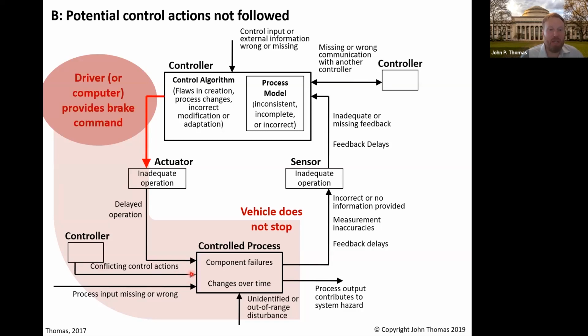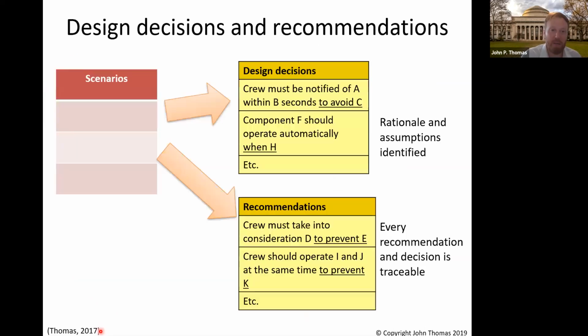That's really interesting. As we get into autonomous vehicles, should the autonomous software at the top here maybe have the ability to override ABS if it knows, look, the priority is to stop? I don't really need steering control right now. I just need to stop. That's a really interesting proposal, one that I don't think has been proposed, as far as I'm aware, on autonomous vehicles. ABS is just always enabled because humans are not capable of making that decision in a panic situation, but maybe autonomy could, and it could make a better decision.